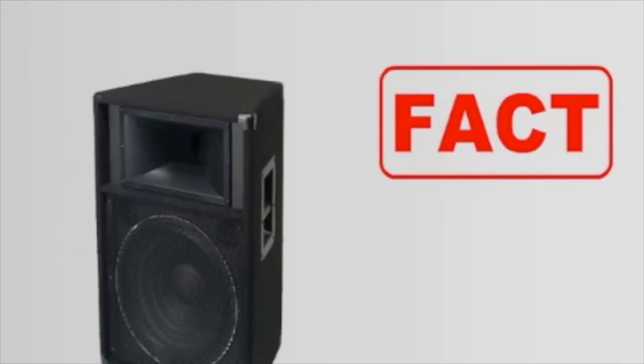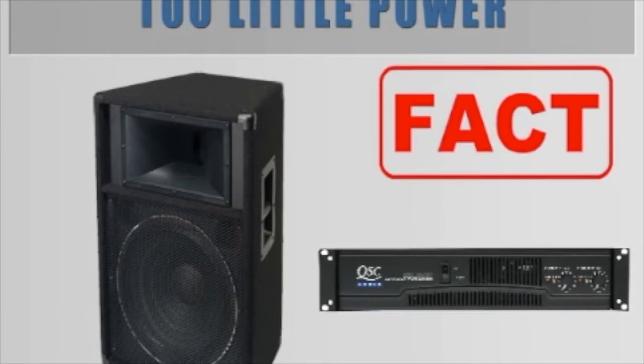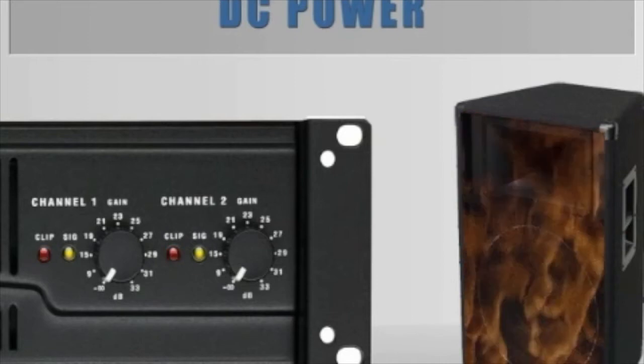A little-known fact is that the main cause of loudspeaker damage is using an amplifier with too little power, not too much. If an amplifier is overdriven and is clipping the output signal, DC power is transmitted across the loudspeaker inputs, potentially damaging the speaker drivers in the process.